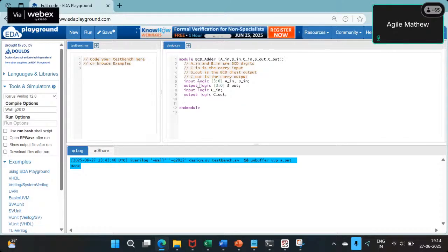It could be taken as reg or wire. That's right. So if I assign to it, there will be no complaint. I don't have to worry about saying it's a reg or anything like that. In SystemVerilog, we can use logic in place of what we did in Verilog, like wire or reg. Yes, yes. That's right.